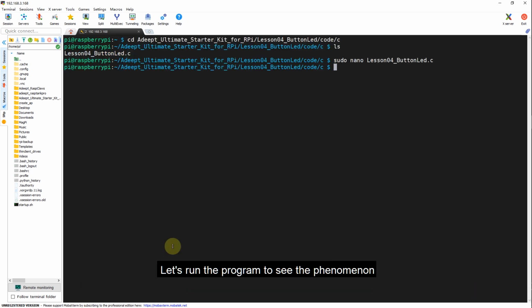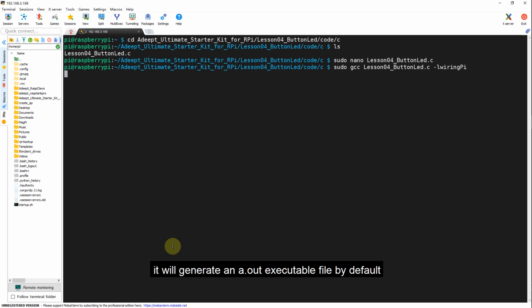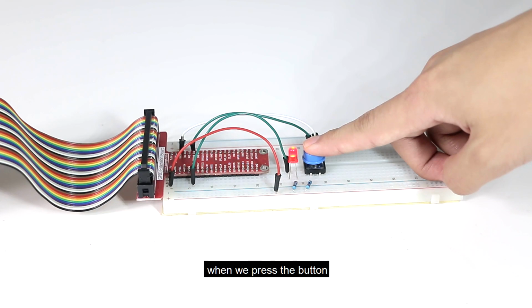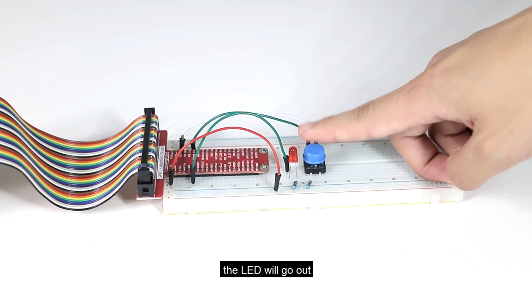Let's run the program to see the phenomenon. Enter the compile command sudo gcc lesson 4 button LED.c -lwiringPi to compile the program. After compiling, it will generate an a.out executable file by default. We enter ./a.out to run it. At this time, when we press the button, the LED will be lit, and when we release the button, the LED will go out.